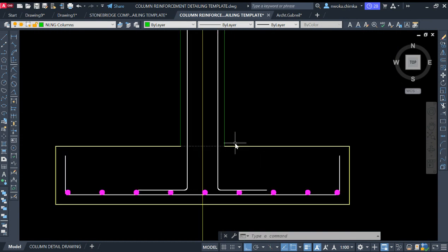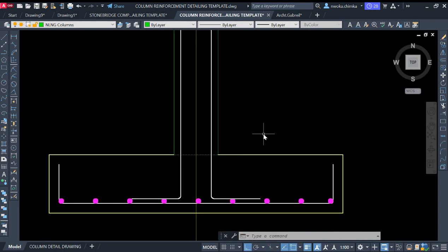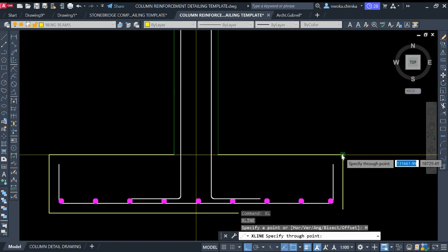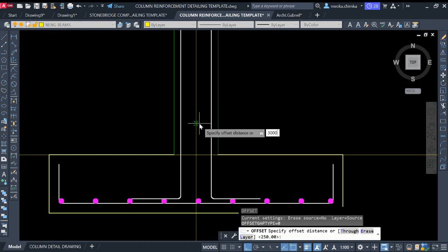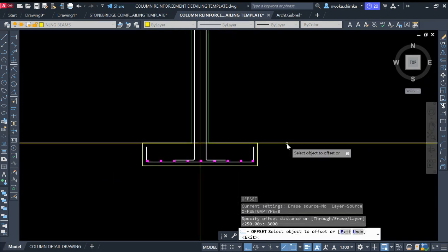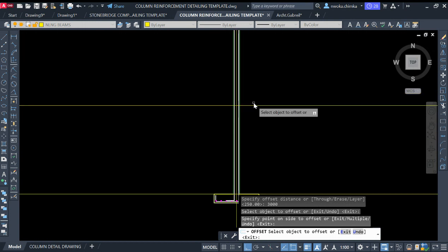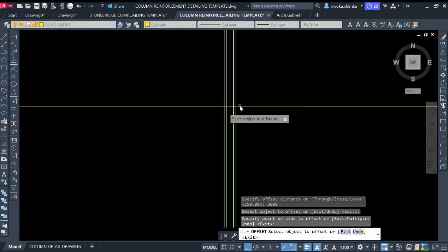Okay, so first of all, offset the height of the building. I'll go to this place and click on beam, then set SL and horizontal, and click on this to offset my building height, which is 3 meters. I'll type offset and 3000 millimeter, press enter, and offset to this place. So this is the height of our building, 3 meters.